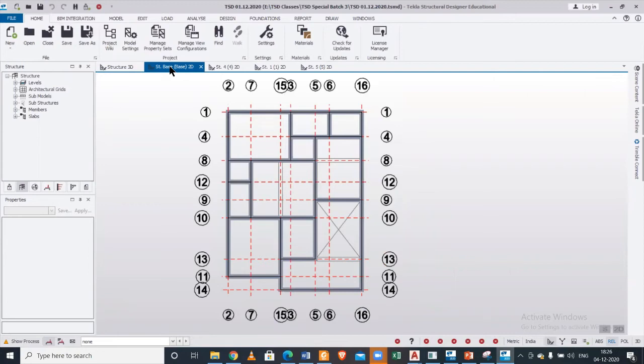loads for our walls here. We have the beams given at all the places above which we have walls, both 5-inch walls and 10-inch walls. So the places which have 5-inch walls, we'll provide a dead load, that is the wall load, in the form of UDL of 5.5 kilonewton per meter. And where we have 10-inch walls, we provide a wall load of 11 kilonewton per meter.